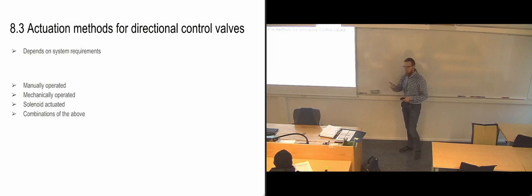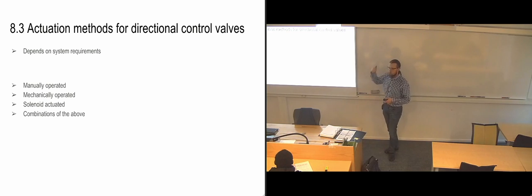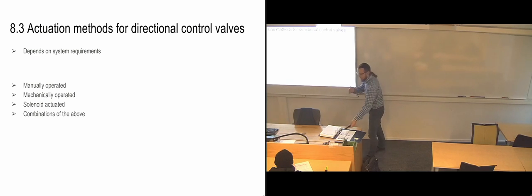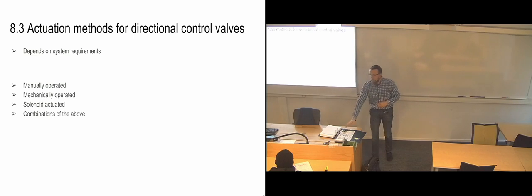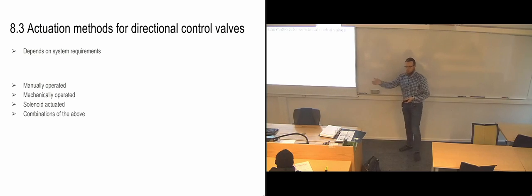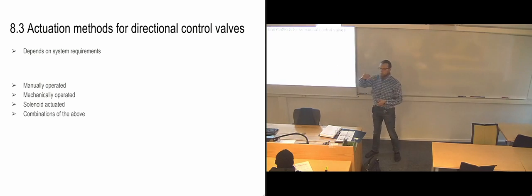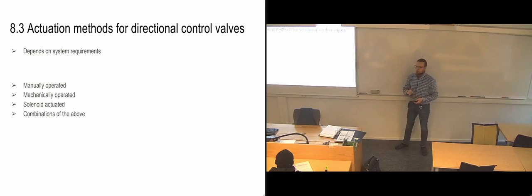This was a pneumatic system. It wasn't a hydraulic one, so it was using compressed air instead of hydraulic oil. But it was still the same principle with the valves and everything. So what it did then was activate the valve, and the valve would push out a piston, which would enter partway into the path of the part that was moving along the conveyor belt. So it would hit the piston, and then it would be turned around. And then it would go to another sensor that would check, is it in the correct position now? And if it still wasn't in the correct position, another piston would be pushed in that would rotate it. And that was the extent of what they had.